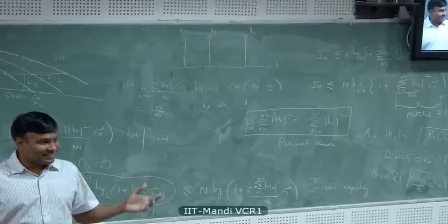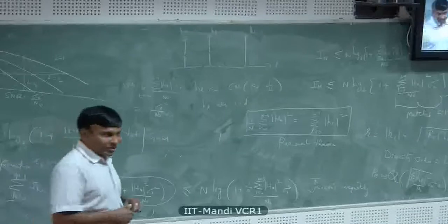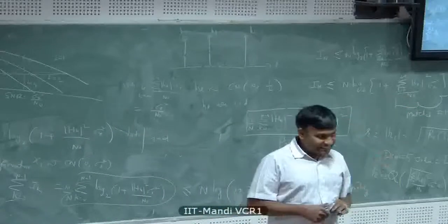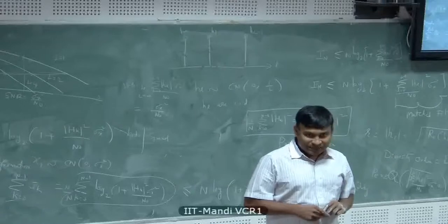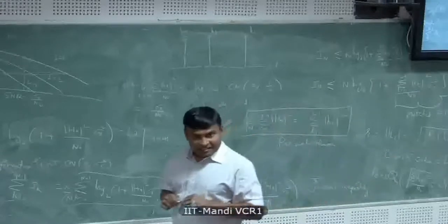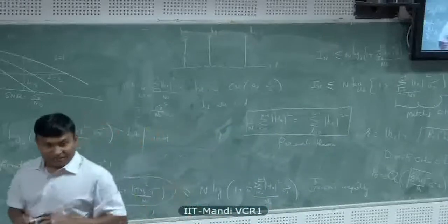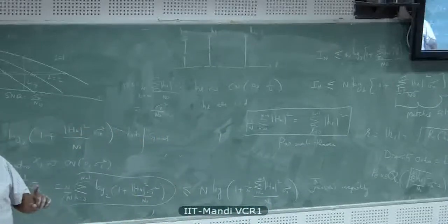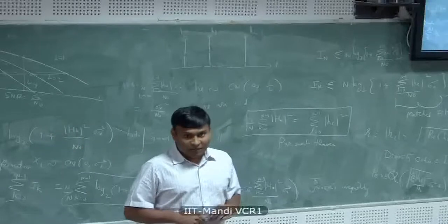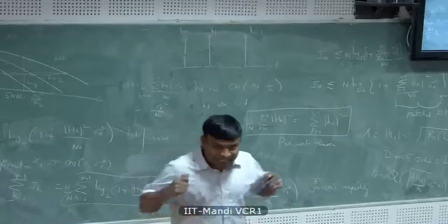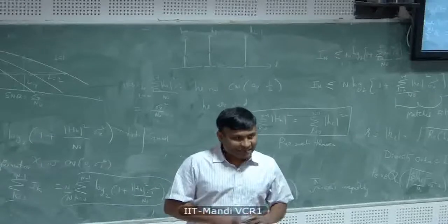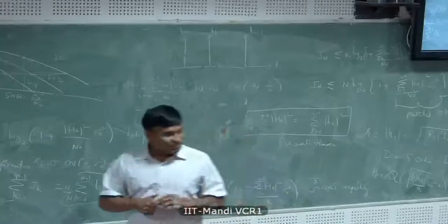That's a simple reason. In that case, what you could do is place these antennas at the transmitter. Base stations can place them sufficiently far apart and get what is called the transmit diversity effect, but you have to transmit the signals with some sort of special encoding, which is called space-time coding or MIMO, because you can't just transmit the same information on both antennas. That won't give you transmit diversity. You have to do something different.